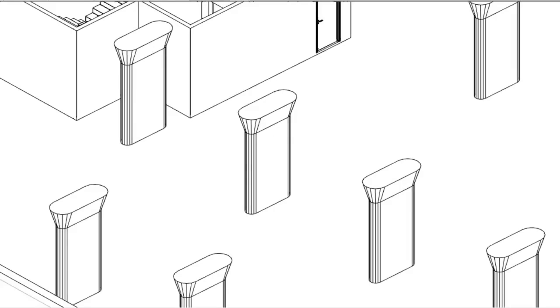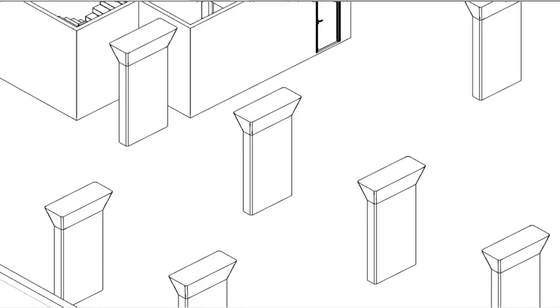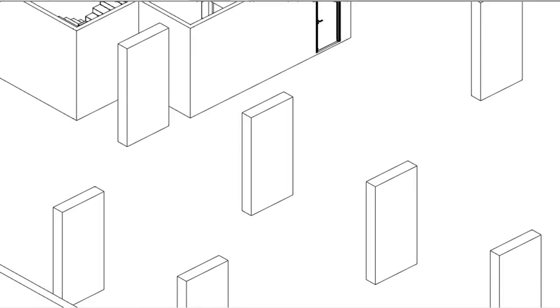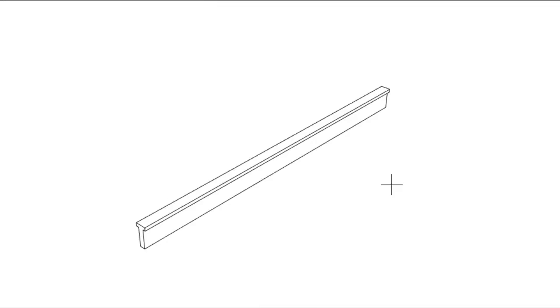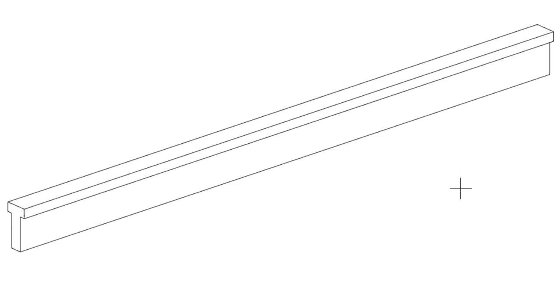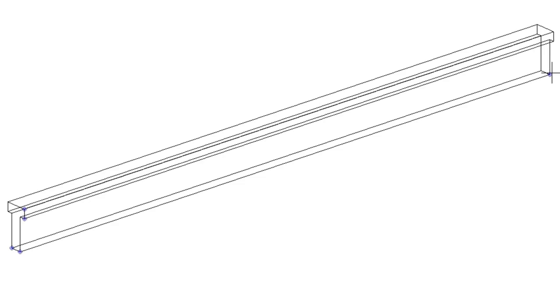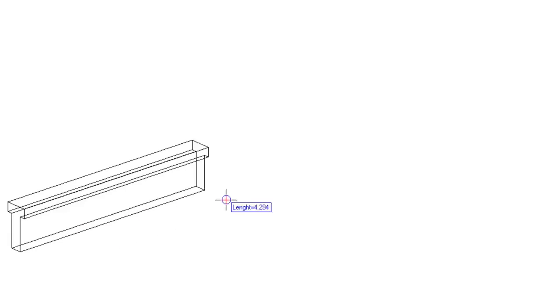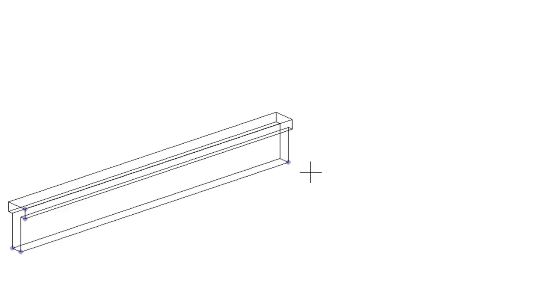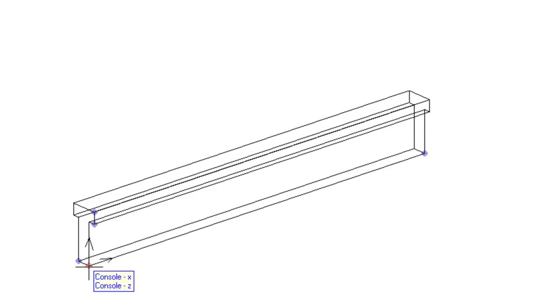You can also change the parameters during the course of the project without having to keep modeling and placing the elements all over again. As a further example, we use a steel-reinforced concrete beam. If required, this can also be adapted by means of the integrated handles. As well as the length, the bearing cantilevers and other characteristic features can be changed in real time and checked.